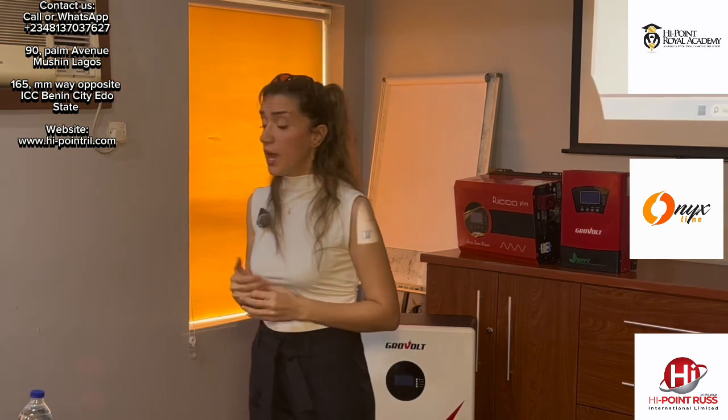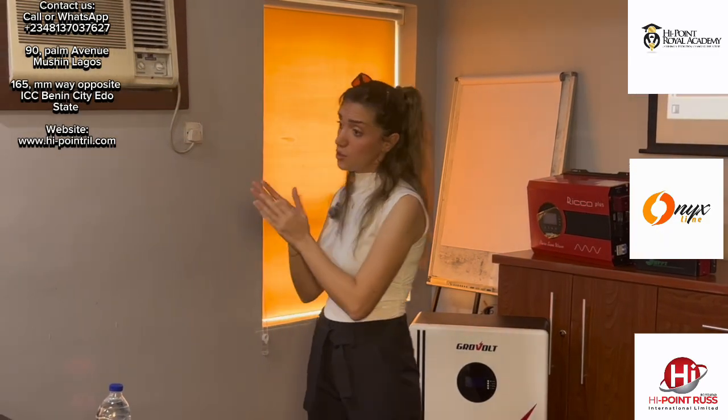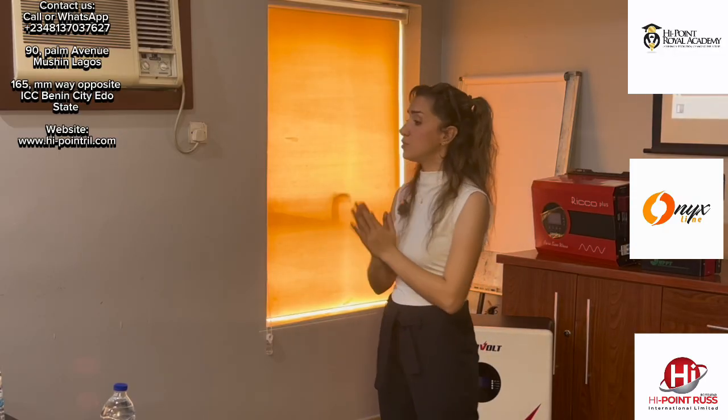Okay, this is what happened. You have to be careful about what you choose, especially for lithium. Also, we have fire protection inside our battery to avoid problems if there is overcharge, over discharge, or overheating in the cells, so I will not have any explosion. You have to be sure. And iron phosphate in general is more compatible with high temperature than lithium ion. So you also have to know the difference between normal lithium ion and iron phosphate batteries.